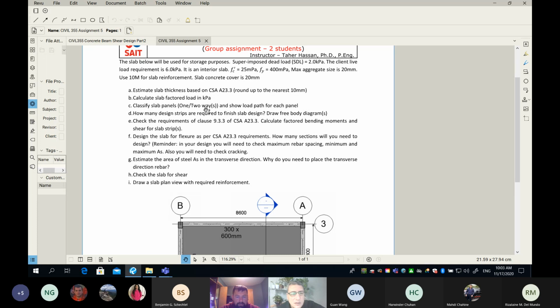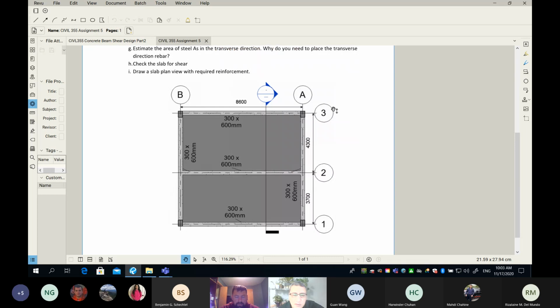So when it comes to selecting the minimum slab thickness based on our concrete manual, you guys know it's not very difficult. There's a table in the code that tells you here is your minimum one-way slab thickness. If I remember correctly, you have to divide your ln by 24. And why 24? Because it is one end continuous. Clear? One end continuous. Okay, so when you divide the clear span, it looks like we have a little bit of difficulty here because we have two clear spans.